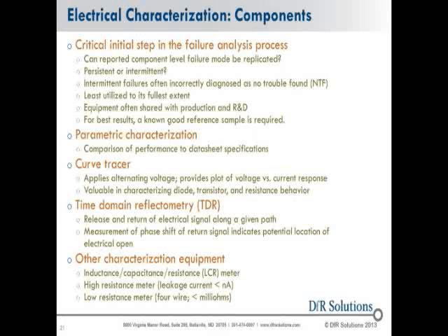So parametric characterization, measuring its resistances or inductances or whatever. If it's a semiconducting active device, an integrated circuit or a transistor or a diode, you definitely want to put it onto a curve tracer and get its VI curve characteristics.